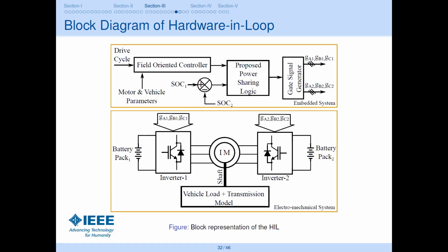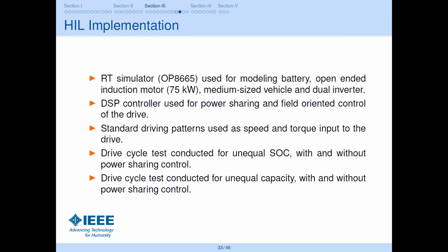And the same power sharing logic, offset power sharing logic, has been applied. So this slide provides a small description of what is being applied in that hardware in loop implementation. So it's basically called hardware in loop implementation. You have a real-time simulator, which is used to model the battery, open-ended induction motor, a medium-sized vehicle, and dual inverter. A DSP controller has been used for power sharing and field-oriented control of the drive. A standard driving pattern is used as speed and torque inputs to the drive.